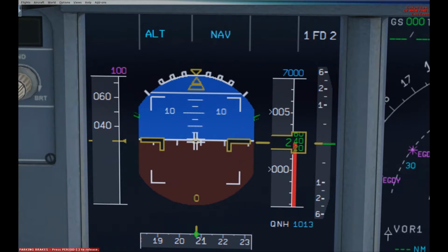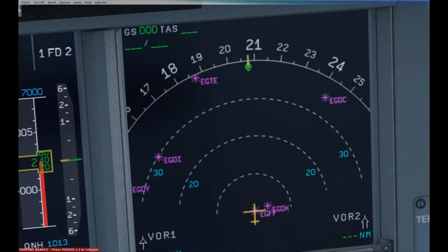The primary flight display shows all sorts of information. Speed indicator, attitude indicator, lateral and vertical ILS glide, altitude indicator, vertical speed, identification of the ILS, heading and track indicator, and air pressure. The navigation display shows your speed as ground speed and true airspeed, wind direction and speed, the next waypoint, and the degrees and distance and time of arrival if and when a flight plan is input into that instrument, the lateral flight path, and the time.